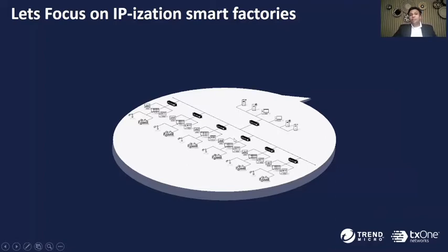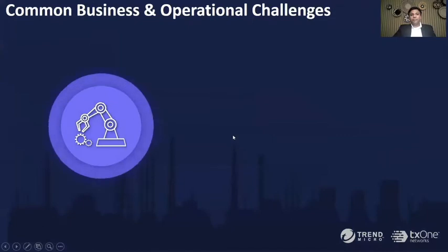Even today, if you see some of the PLC devices we see within the OT space, they come with a static IP address. So you cannot go with a full-fledged VLAN approach or segmentation approach on a layer 3 level in these IP factories. So we may need to take a layer 2 approach where we can create segmentation, but you don't affect the architecture of the communication protocols and so on and so forth. So how do we do that?